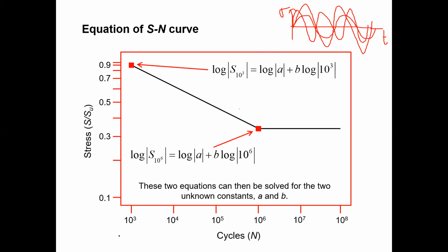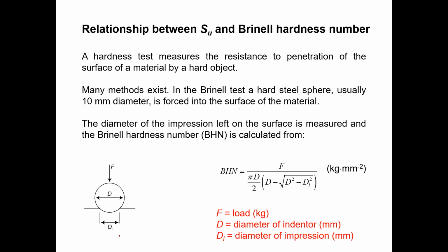Okay, so this is the Brinell hardness and the endurance and ultimate tensile strength relationship. They explain what the Brinell hardness is. You know there is an indenter, and with a force, that indenter will be pressed onto the material. That force should be a constant, known value. There are actually tables for that. You can select the load value, 10 kilonewton or 5 kilonewton or 20 kilonewton.